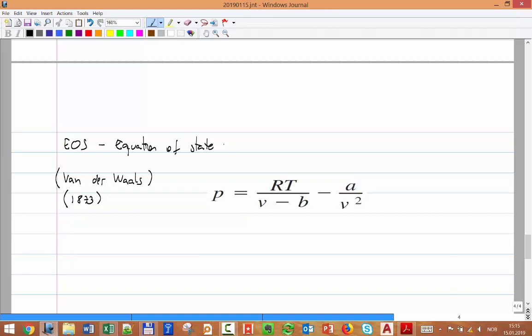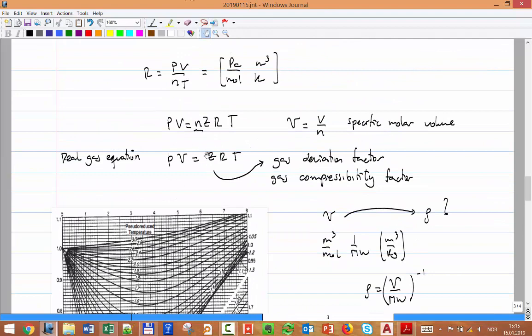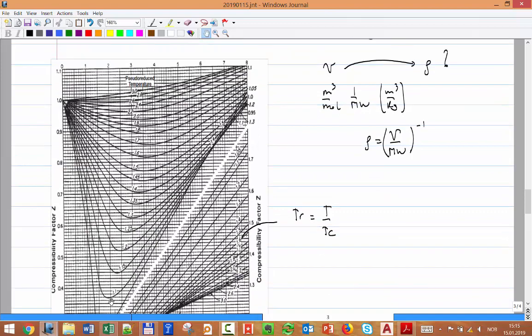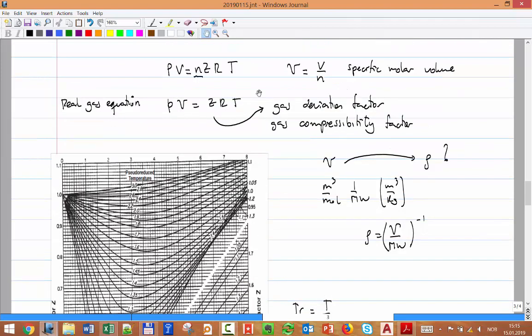So what we use for all of our engineering calculations, also in many other engineering areas, is what is called an equation of state. Basically, because that equation is very simple to use, the problem is trying to define the behavior of Z. It's relatively easier to do for a gas, but when you enter into a mixture, it's extremely difficult to find a relationship for Z.